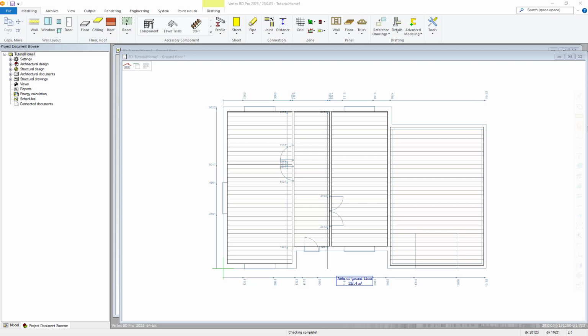In order to create drawings and ultimately NC data for the framing of horizontal structures, it is necessary to panelise the area first. Larger areas can be split by using break lines to create smaller panels. However, it is possible to skip this step and move on to panelising the whole area if you would only like to add one panel to any particular area.